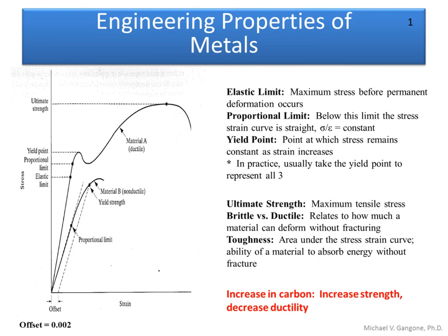All right, engineering problems. So again, this is probably more along the lines of something that you could see for the FE exam, in relation to the engineering properties of metals. In particular, if we give you a stress strain curve, can you point out the yield point? Can you point out the ultimate strength? Can you point out the yield strain? Can you determine the elastic modulus? Things like that. That's really, I think, a big part of what could be asked on an FE exam: what are the different properties of metal if you're looking at the stress strain curve, right?